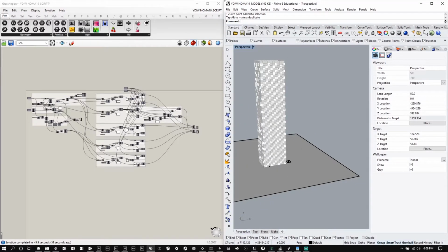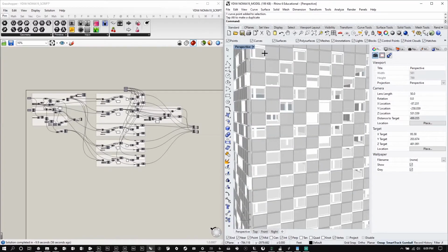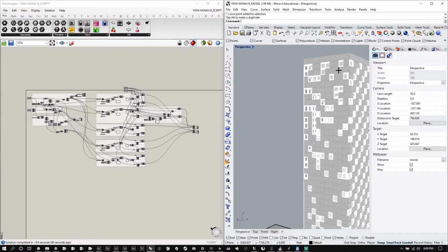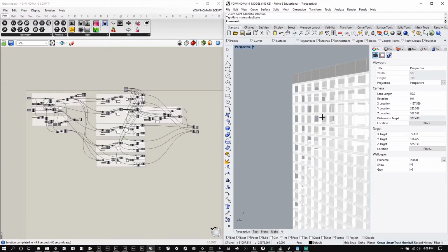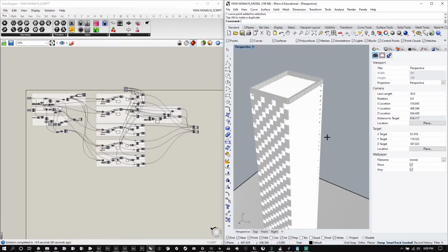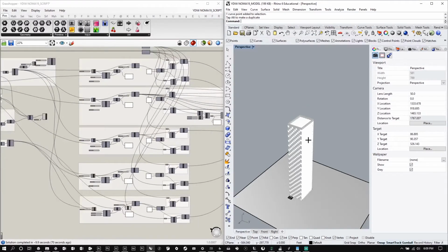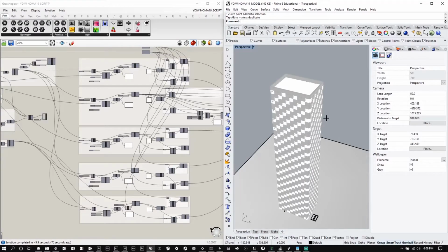And you can do it a number of ways. In this case, I'm using a true false pattern or a true false false to create that pattern. Over here, it's the reverse. Over here, it's just one of the panels to create glazing on the north face. So you can really pattern the facade based on the different parameters that you use. So if you want to see me building this, check out the video online. But this is the freedom that Rhino gives you.